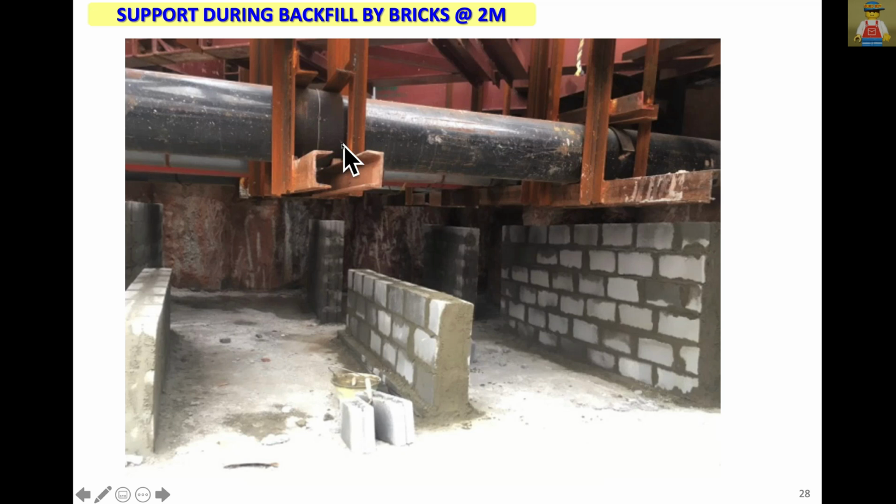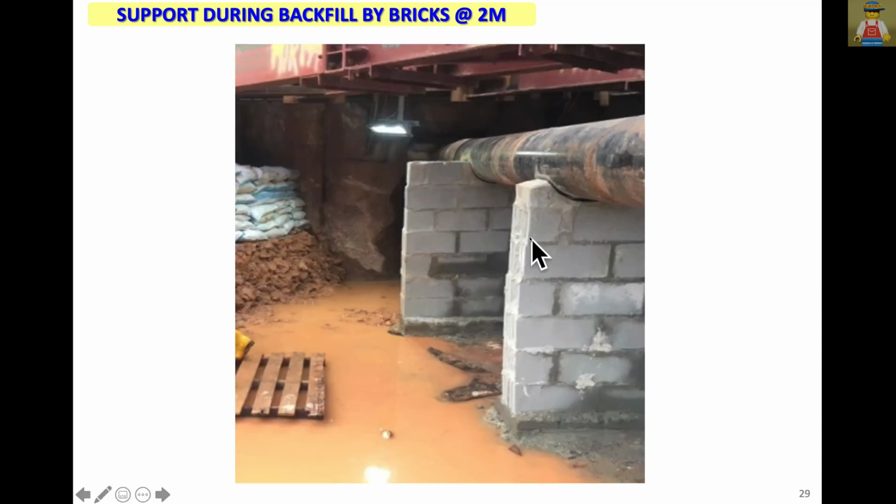The next is, once you support during the first layer strut or second layer strut or third layer strut, depending on where they are, then once you finish all the structure below, then go up as the bottom-up method. You finish all the strut, all the RC structure, then backfill. Then when it comes up to the location of the utility at the last, how do we remove the angles? In order to remove the angle, we have to support from below every 2 meters. So normally we can use brick. Then after installation of the brick, the angles can be removed.